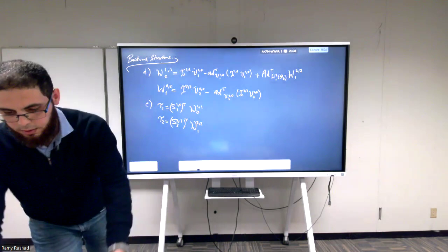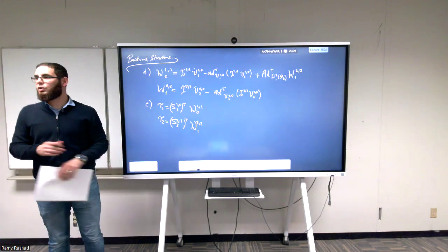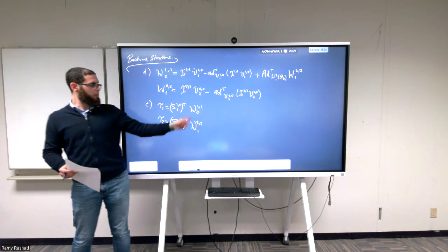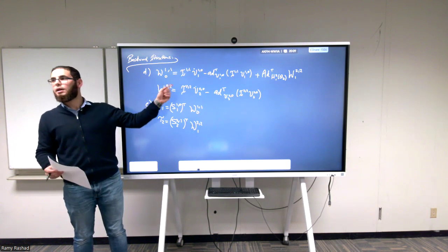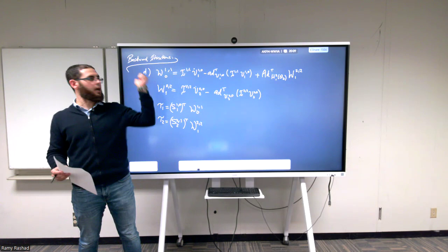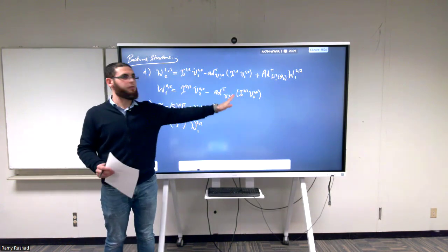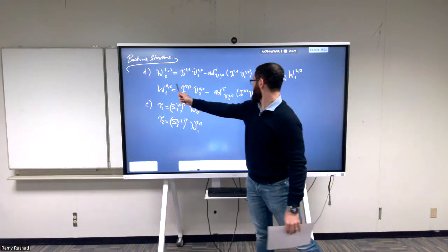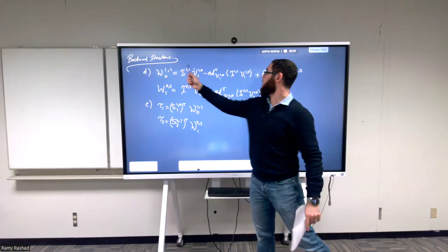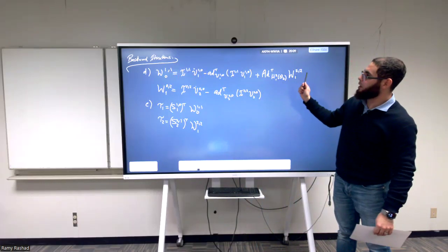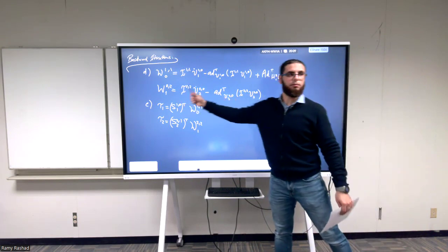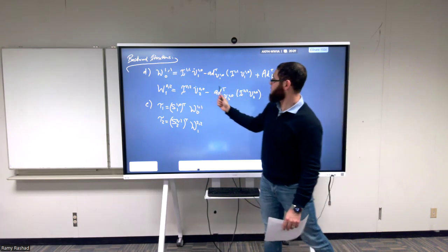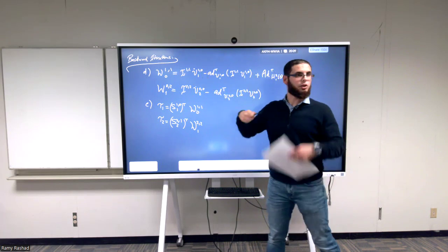But now to calculate the reduced dynamics, we would start again from these equations. Again, you would start from tau 1 and tau 2, plug in the wrenches from these two equations, take the v dot and v dot from the two previous slides, the v and the v from the previous slides, and so on and so forth. You see now that we will start to have some coupling, right? Because when we're calculating the 1 and 2, we're calculating the 0 and the 1, which is the one in between, we start to get some expressions. Yeah, this one, you see, it's replicated here, so this one is also here. And then I start to get some relations and some coupling between the v dot and the v dot in the same equation, and so on and so forth.